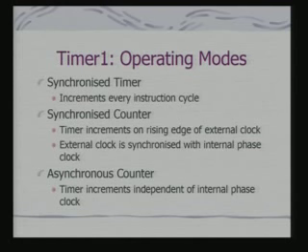That is when it is perfectly synchronized with the processor clock, and you can count the number of instructions getting executed using this timer. It can also be used as a synchronized counter, and in this case the timer increments on the rising edge of an external clock. But this external clock is synchronized with the internal phase clock.